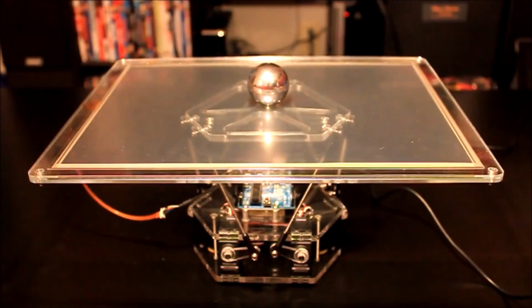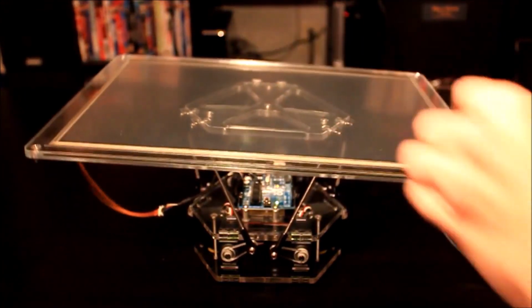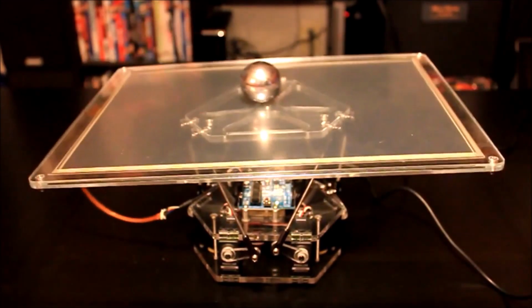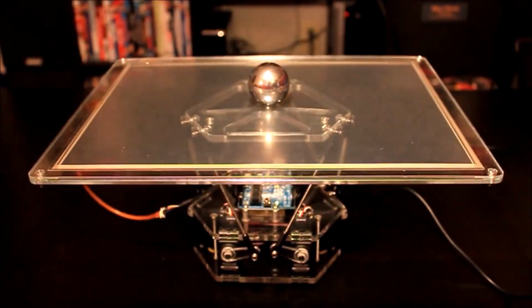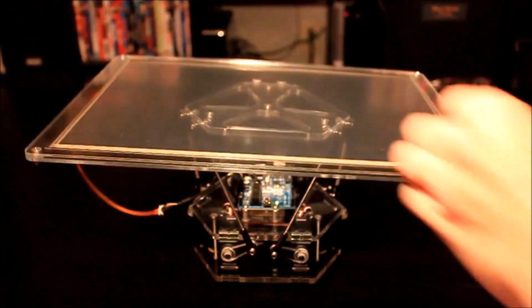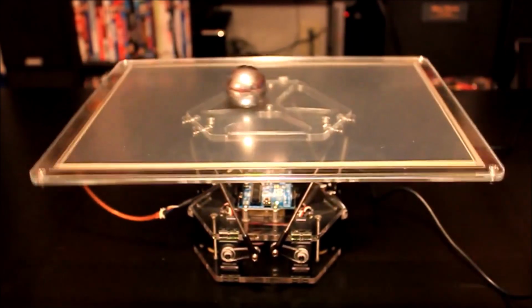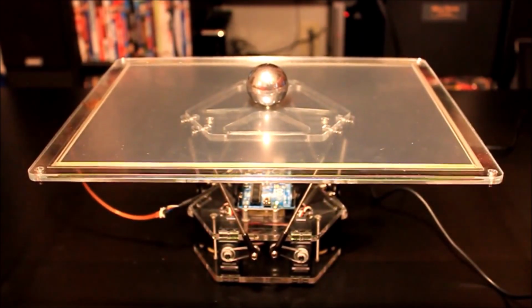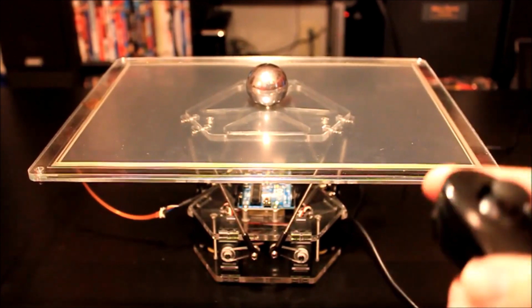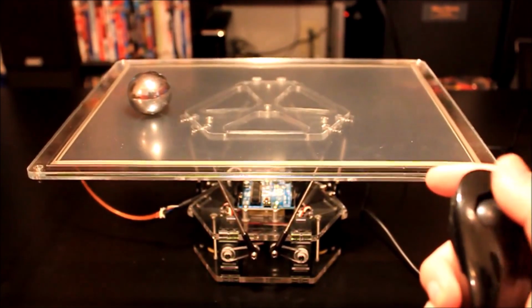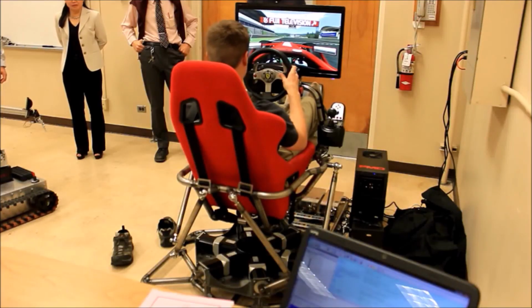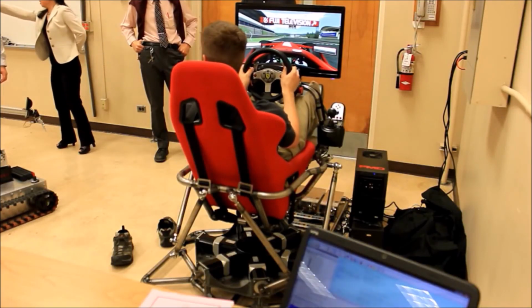With Stewart platforms, you can either use a rotary motor or a linear actuator to actuate those lengths, and they're aligned or configured in such a way where you get the 6 degrees of freedom. So none of the joints are redundant. Redundant means that the motors are running on the same axis.